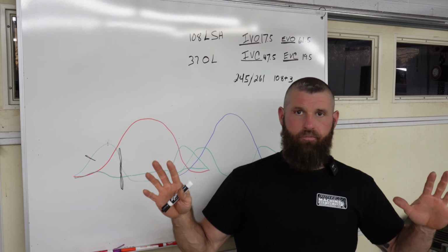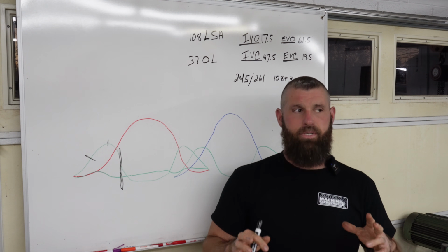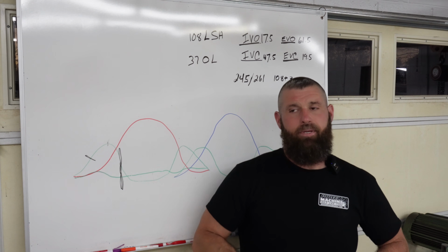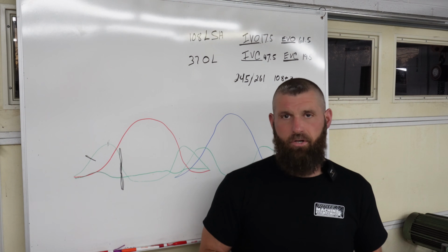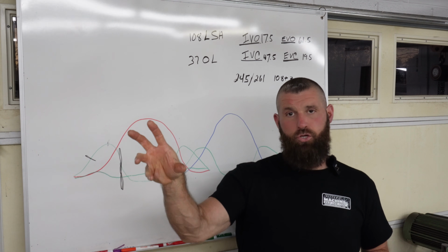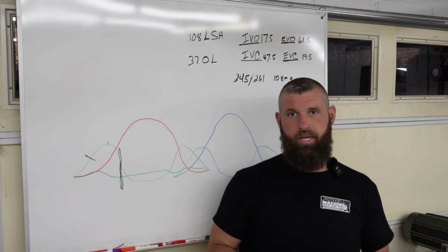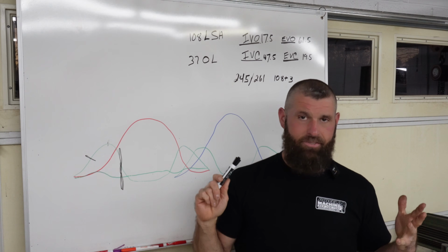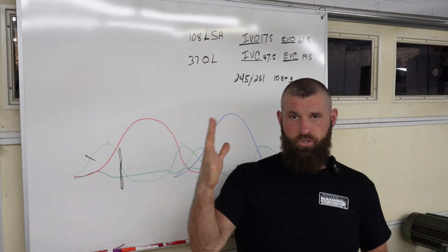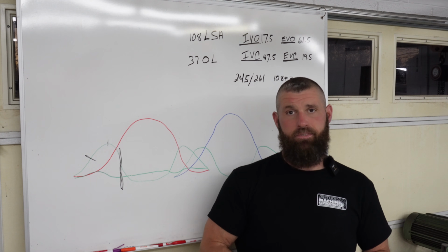When we get out of that, it's so bad that it's just not usable. This is why I say there are all kinds of formulas out there that work okay, but nothing is perfect. If the math says we need 325 degrees of duration because you are way under cylinder headed for your application, we can't just put a 325 degree cam in your motor. It's not going to work, right? You need to fix the cylinder head. And that's just how it is.